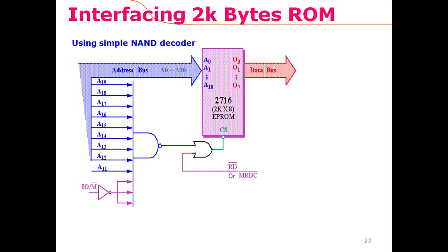So remember that in these microprocessors, the address is a 20-bit address. So we need to decode the 20-bit address in such a way that only the locations are properly addressed inside this chip. So 2 kilo locations are valid addresses, and those 2 kilo addresses should be properly decoded so that each address identifies a location inside this memory chip.